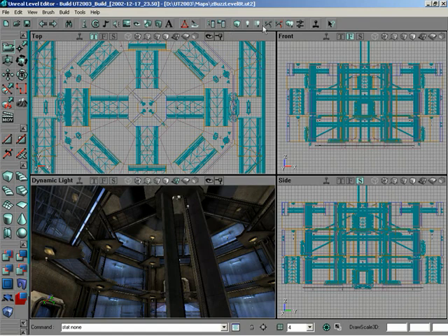And then this set of buttons controls various aspects of rebuilding. You have a few shortcuts to rebuilding, like say just geometry or just lights or just only the changed lights, your paths, meaning the navigation that bots will use to find their way around the level. And finally, you have a button that will let you build everything: your geometry, lighting, and all your paths. And finally, you have the button to set where you go and grab all your settings, like what levels to build stuff to, what format to save the light maps to, etc.